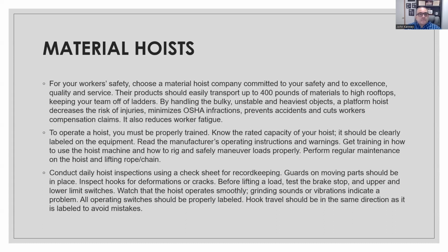Material hoist. For worker safety, choose a material hoist company committed to safety and excellence. So if you're hiring somebody from the outside world to do your hoisting, crane operators, make sure that they're fully up to date. And your professionals 99.9% of the time are. Make sure they have all their paperwork, they have their training, they're up to all the OSHA regulations and everything you need for hoisting. This includes somebody operating a low lift, besides a crane, or other ways of lifting up with hoisting equipment to your project. You need to conduct daily hoist inspections using a check sheet for record keeping.